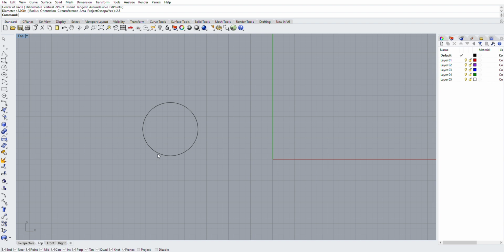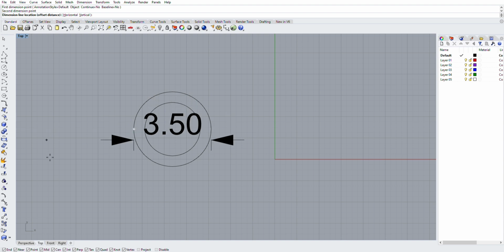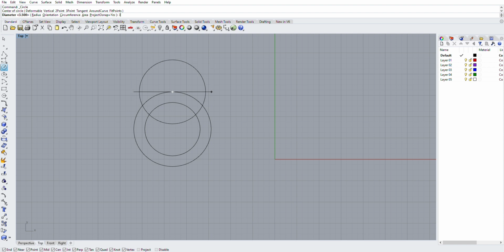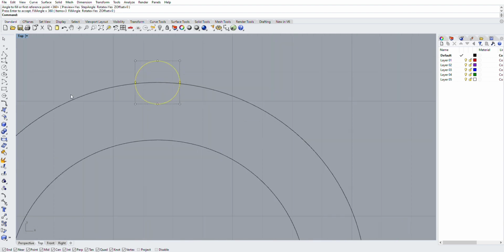Now let's take a different approach. There's pretty much 2 ways to measure the bolt patterns, and we have to worry about the center dimension. Now, on say a 3-bolt flange, that's what we're talking about here, but it doesn't matter if it was 3-bolt, 5-bolt, 8-bolt. It would be just like a bolt pattern on a car, say 3 on 3.5 inch. So if we set our 2.5 inch center hole for our exhaust, we put a 3.5 inch circle. If we click anywhere on that outer circle, put a 3/8 bolt, and do the polar array command, we end up with 3 bolt holes that are on the 3.5, just like your axle bolt pattern.